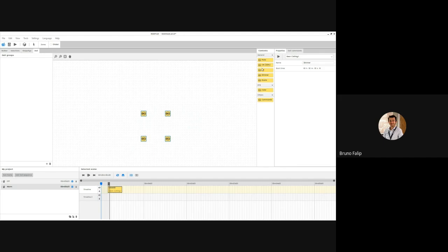So we should maybe rename this label here. In my case, if I want 100%, I need to put the dimmer value here. You select it, same again, broadcast, and open DALI command, and you can, for example, enter 100% with a 2-second fade time. So now it's working here. I have my lights on, and it took 2 seconds to reach 100%.